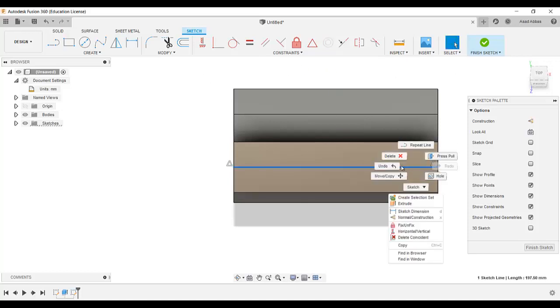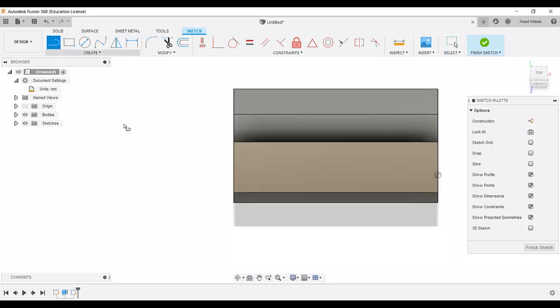Once again I am going to do that so you can understand it. Select line, we needed to trace the middle point of this line from here to here. So just go on that line, and when you are in the middle you will see a little triangle symbol. That means this is the midpoint. So select this one and also the midpoint of the line from here to here. As you see the line is showing a triangle. So this is the midpoint. So on both ends you can see the constraint of midpoint.